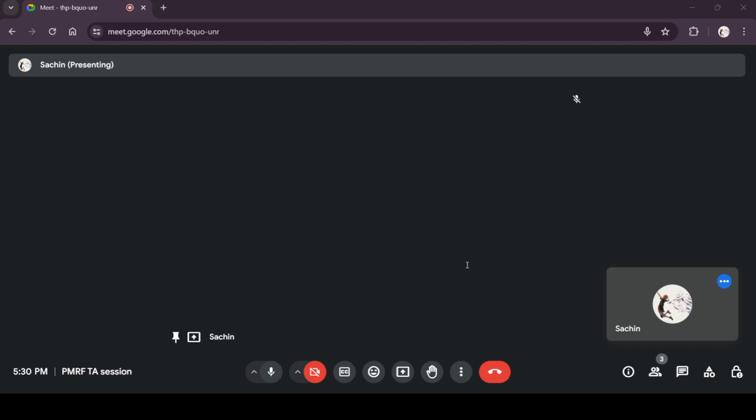Q14 will be turned on and D out bar will be 0. This is an NMOS, so if this is on, it will pull down D out to 0, and if this is on, it will pull down D out bar to 0. When D out is pulled to 0, D out bar will obviously be pulled high. The exact working you will have to look at in the lecture to understand how it happens.